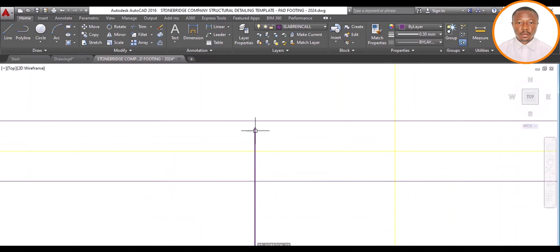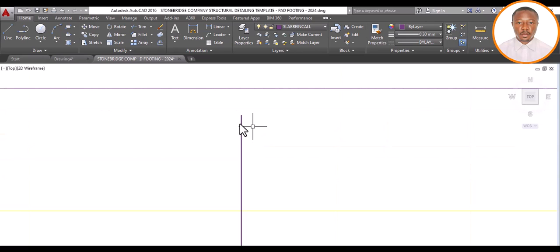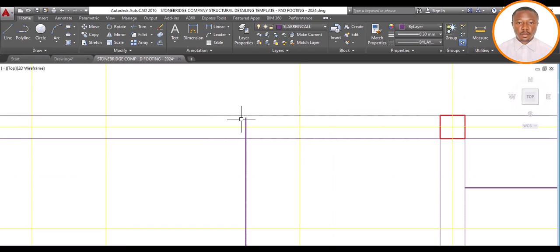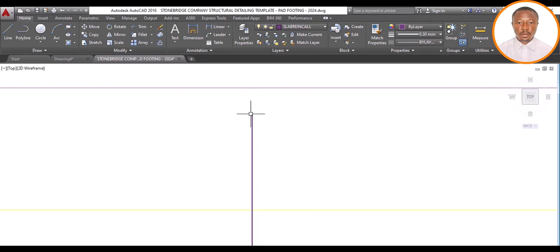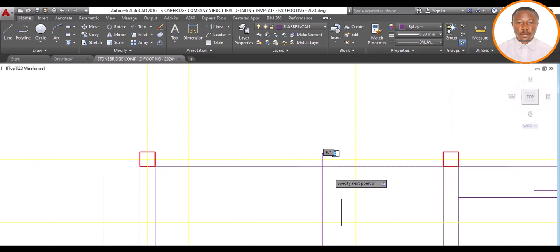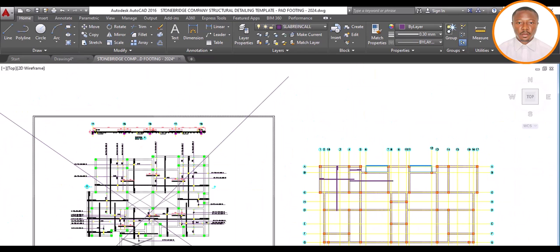Now I extend it. I brought it in. Then also, we have taken our 25. As you all know, definitely there's formwork. So the distance between the formwork and your reinforcement is that 25 we are talking about. So I come here, I pick my line. At this point, I take my thickness, which is 100. You remember how we got our 100? Enter. Then come back and take our return bar, and remember our 50D, which says 600. Enter. So escape. You can see we have this.